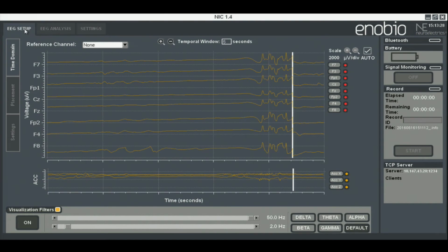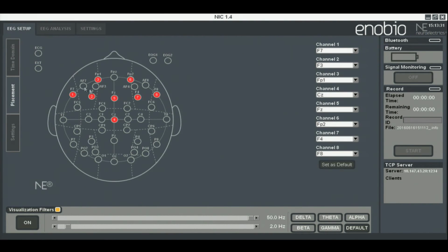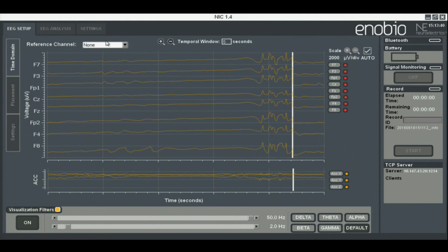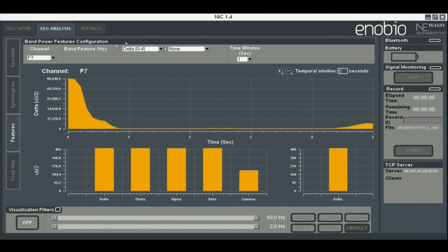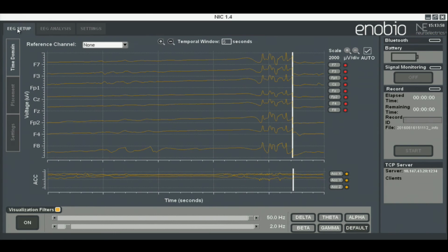So once you decide what are the channels you wanted to connect, you just have to change this depending on the channel of interest to you. Once you set this, then it's a data acquisition. You can start the acquisition on your own, and whatever analysis that is provided here, you can use that basic analysis in this. And since the raw data is with you in the .edf form or EDF form, that can be taken across for the analysis environments. Any tool you can use it to do the processing.